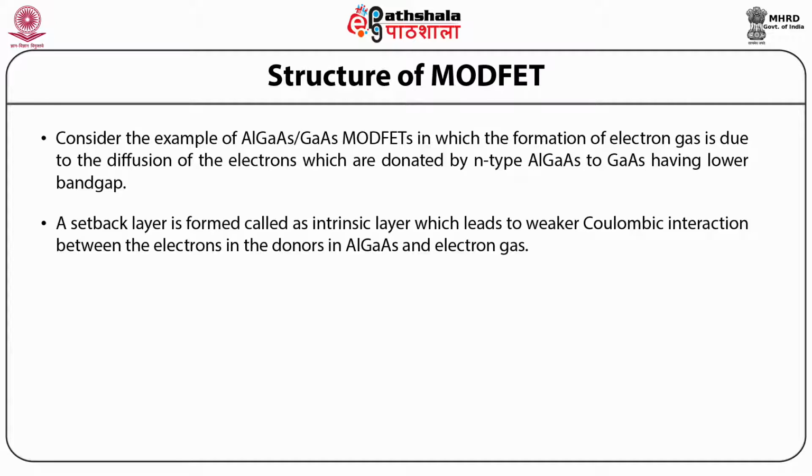Enhancement in electron confinement can be obtained by raising the aluminium arsenide mole fraction in aluminium gallium arsenide, which leads to a large discontinuity in the conduction band between the gallium arsenide and aluminium gallium arsenide.